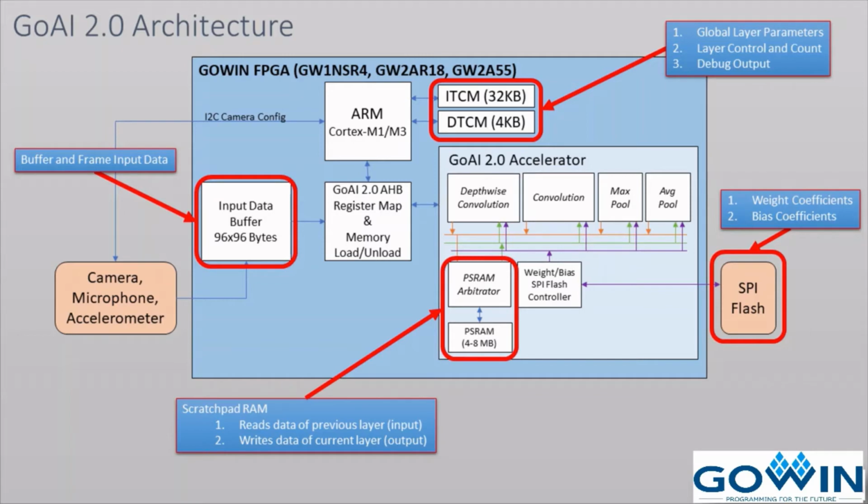So from the Cortex-M processor, you can actually read out the individual layer data from each layer and debug that way, which is really nice. A lot of times I'll do that during debugging, and I'll compare it to the layer output data of running the same flat buffers file on my PC, and I can make sure that I have a one-to-one match.